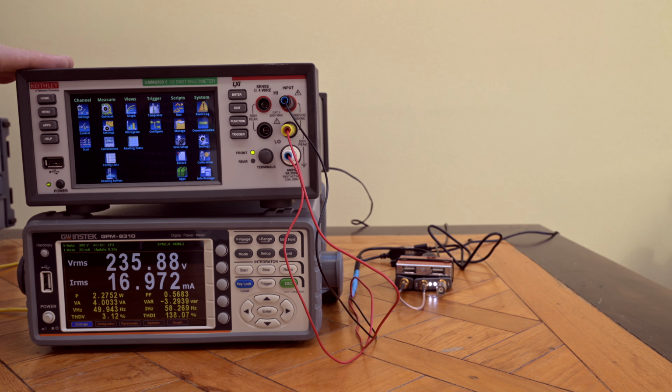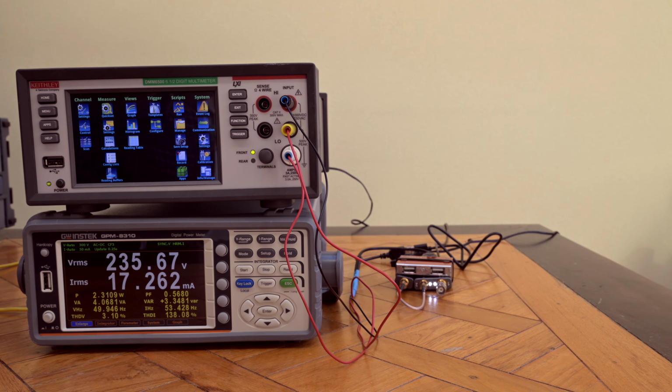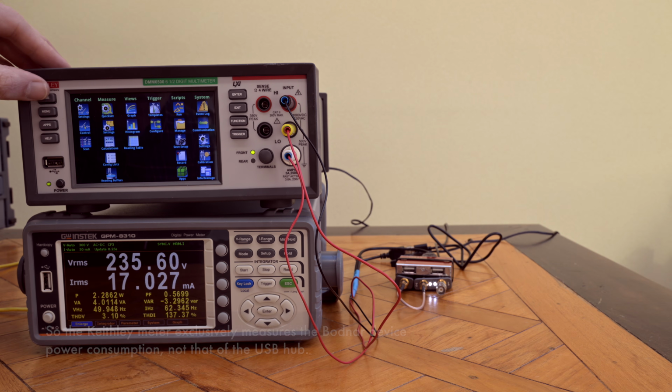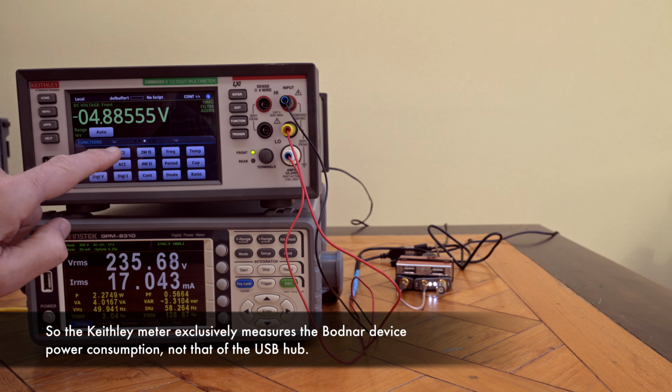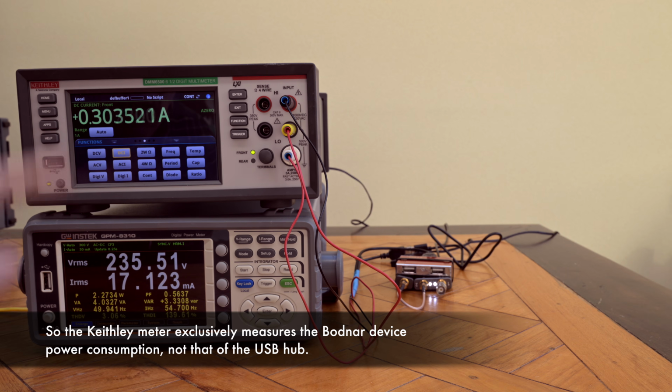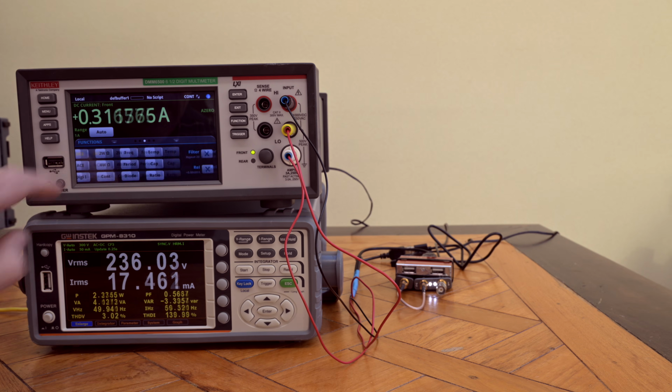So I connected up here the DMM, where I can measure both power and voltage. I made a Y cable to the USB connection here, so the voltage is going to be reverted. So let's go and see. Voltage of 4.8 volts, so it's plus actually. So that is just fine. Let us see how much power it is drawing. It seems more like 300 milliwatts. They published a maximum of 250, but it seems to be a little bit bigger than that.